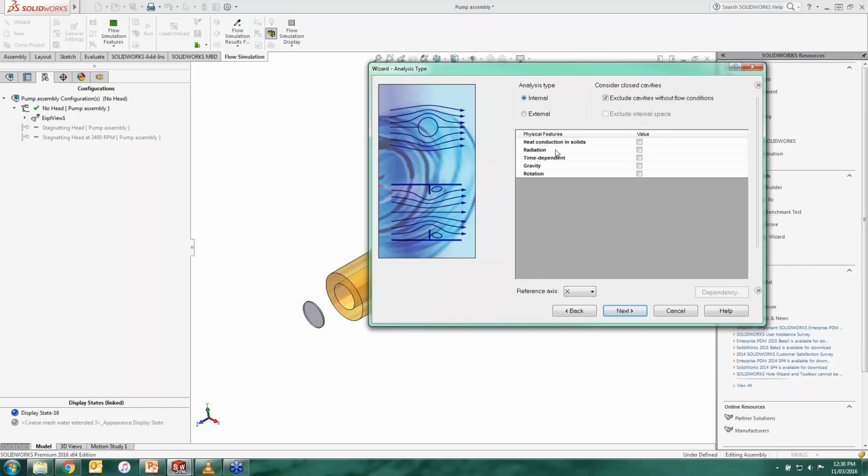If you have a steady state or transient, if gravitational effect is active or not, which we have covered almost all of this in the other examples and webinars we had. But the main area of interest for today is rotation. By ticking on that one, you're telling the software, I'm either going for a local region averaging, or I can go for local region sliding.